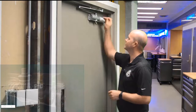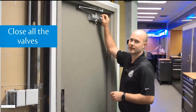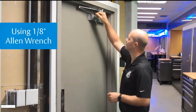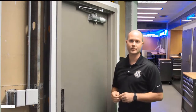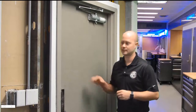The first thing we want to do is close all of our valves in our closer body, rotating them clockwise, so to the right, with our 1/8" Allen wrench. The next thing we want to do is actually open our door. So, I didn't mention earlier, we need to do this with the door closed.